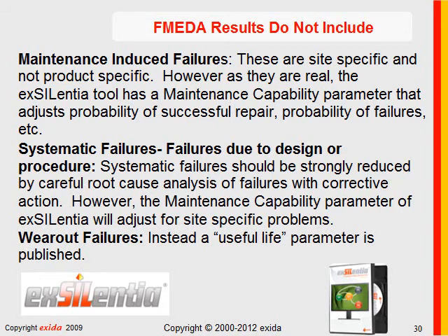There are certain things that are absolutely not included in FMEDA results that everyone must understand. Maintenance-induced failures are not included. This is primarily because they are site-specific and not product-specific. I don't want to diminish the value of having site-specific maintenance-induced failure data, and that's an extremely valuable thing we can get from field failure data collection.